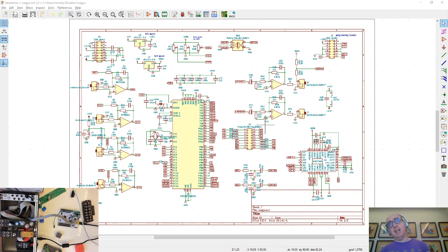They're only like 20K, whereas for I2C you probably want 2 to 5K, sometimes even less. So basically it's really soggy if you use the in-chip pull-ups, so you have to go slowly. But I looked at the data sheet, turns out it doesn't care how slow you go. So I'm going to bit bang the I2C on this stream, and it works, so thank God. So I got away without the pull-ups, which was a bit silly.